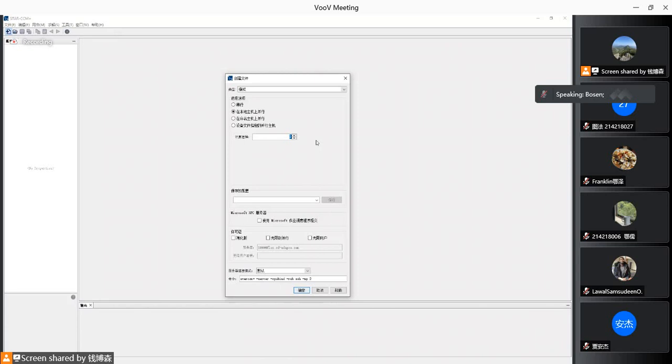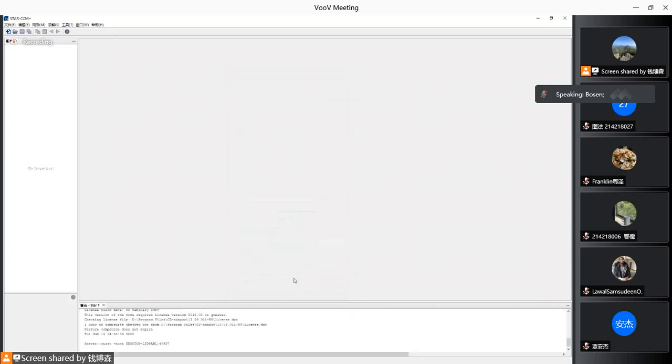Okay, the best case scenario is that your system is incredibly slow throughout the computational process, such that you can do nothing, literally nothing at all. And after it finishes its calculation, it may be several minutes or even several days or weeks before you can finally get back the control of your system. Okay, so that's the 2 points about the parallel computing in here. So now I will give it a 16-core parallel due to my high performance computer in here.